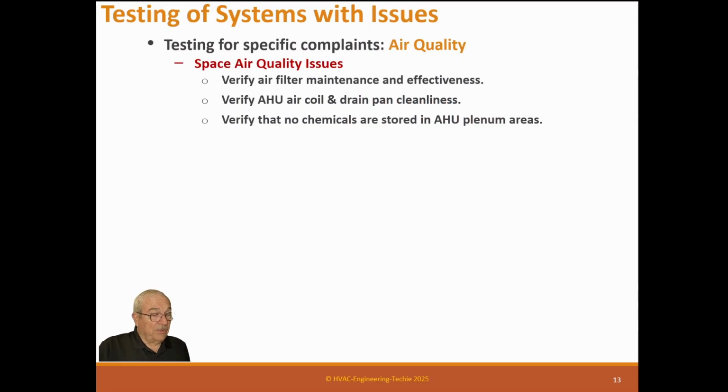A lot of return airs, the rooms themselves are part of the return plenum. And you put chemicals in there, guess what? You're just pumping chemicals through the whole building. So they shouldn't be storing anything in an air handler room. Even if it has ducted return, they shouldn't be storing it.